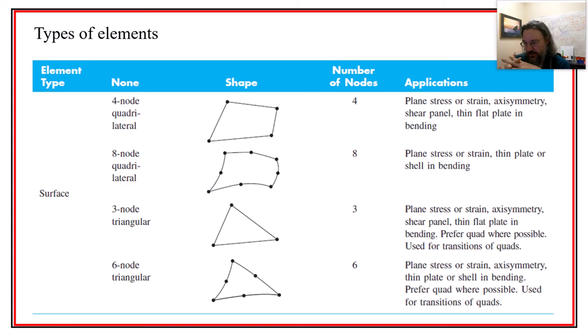Now, SolidWorks Simulation might make it deceptive because they really are only using one element type for solid stuff. They do have a shell element. It's not a great one. You could do a thin-walled thing by representing surfaces with a shell element instead of having this triangular tetrahedron thing. They can get away with doing that because elements have really come a long way, and the stuff underneath the hood, the element formulation, has had lots of little tricks and things over the years.